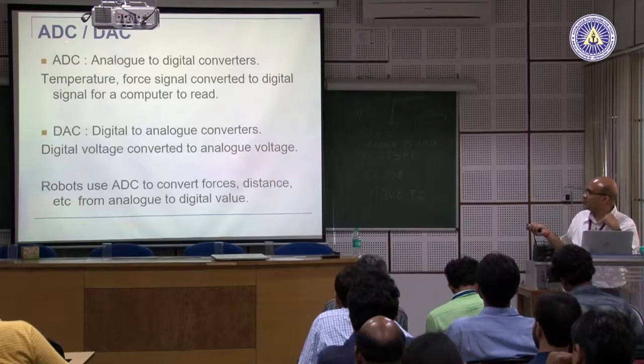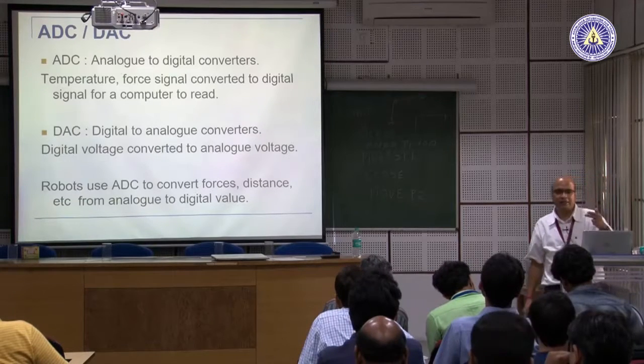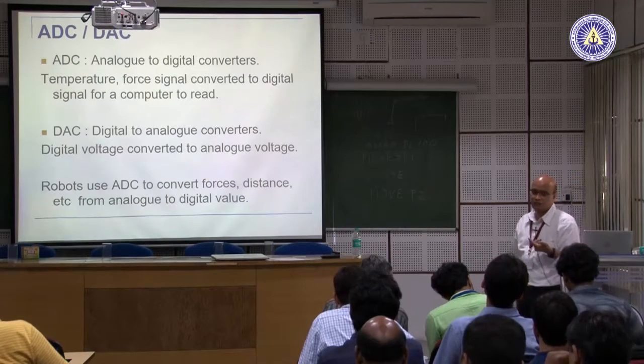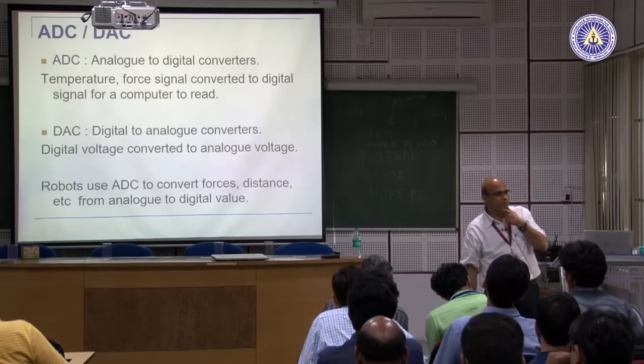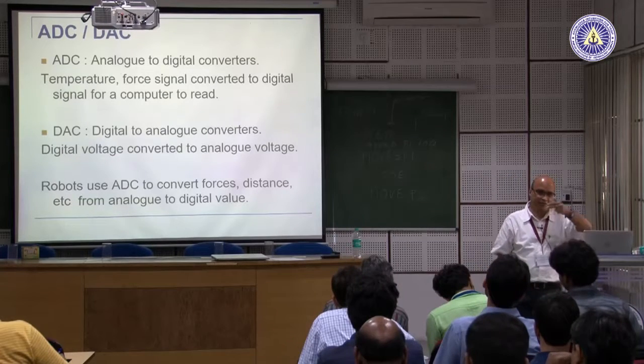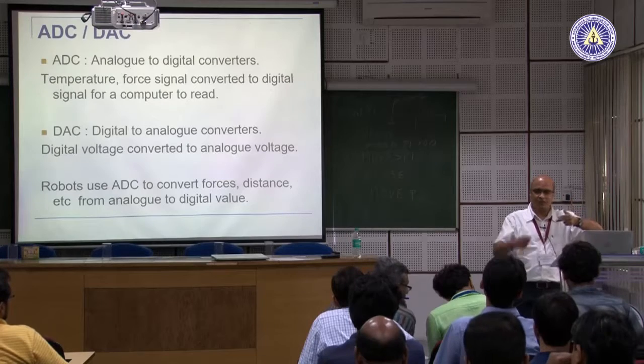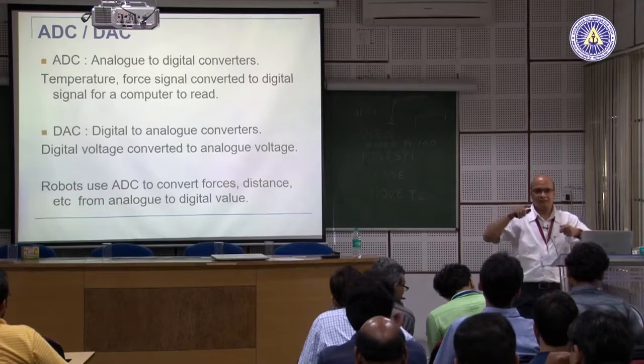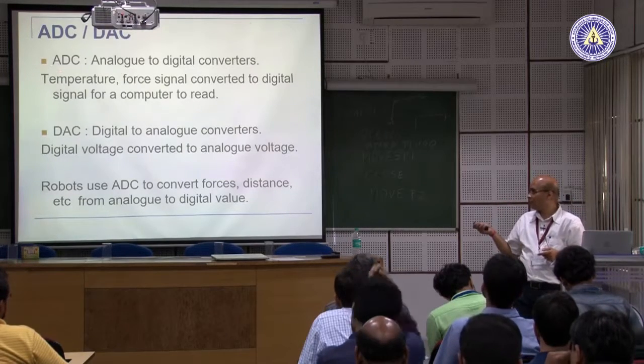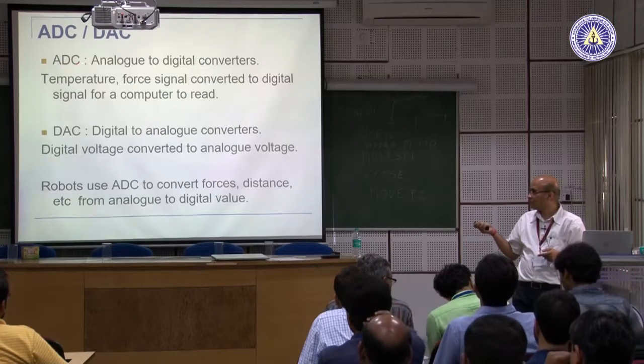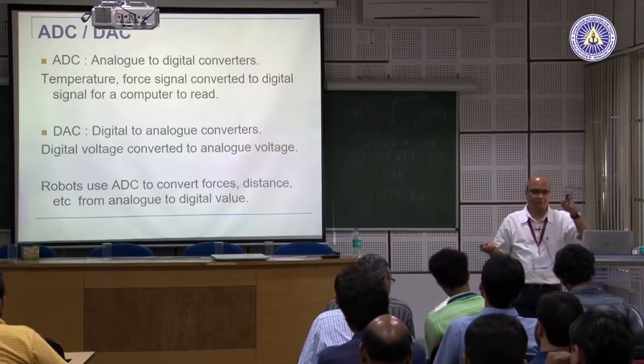conversions are taking place. So, any sensor which is giving an analog signal like pressure, temperature, force, then proximity is another one, okay. It is a continuous signal with respect to time. So, it is digitized by using the analog to digital converter, and then it is given to that particular channel, okay.